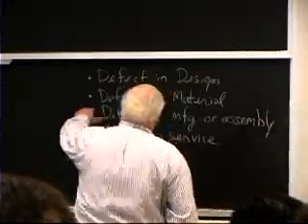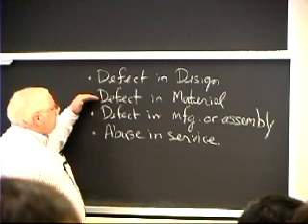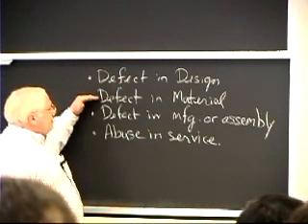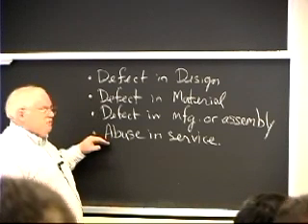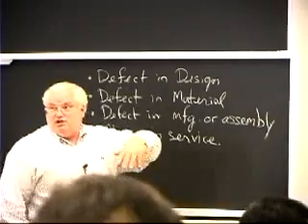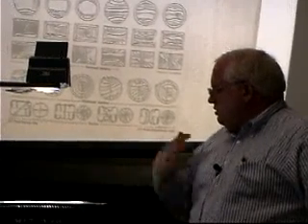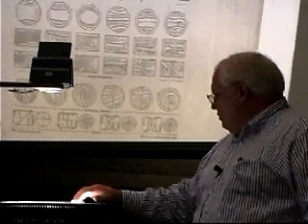So you're going to look for defects in the material in that low stress fatigue fracture. If you don't find that, then you basically have to assume there's some sort of abuse in service. Defect in design: if you see something that's really highly loaded and it's not supposed to be highly loaded, well, that's why it failed. Turns out medical implants, no matter what you do, end up being highly loaded because there's just not enough room in the human body to put enough metal there to support things. In any case, there's lots of things you can tell.